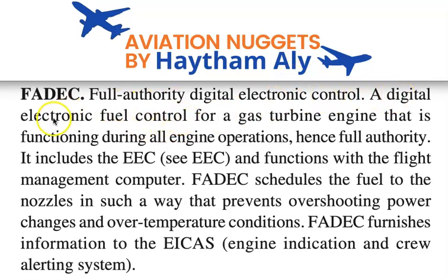The main function of the FADEC is to control fuel flow. A digital electronic fuel control for a gas turbine engine that is functioning during all engine operation. Yes, the FADEC controls engine operation during all phases, during starting and during transient operation, not only during starting or only during engine transient operation.